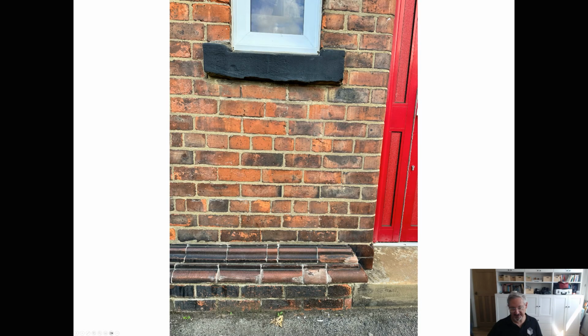So what we're going to plan to do is English garden wall bond, which is basically you have, I think they're called stretchers, these sideways bricks. So you have 3 or 4 rows of stretchers, and then a row of headers, which are these, and then you have 3 or 4 rows of stretchers and then a row of headers. So I think that's the way we're going to build the wall, English garden wall bond.